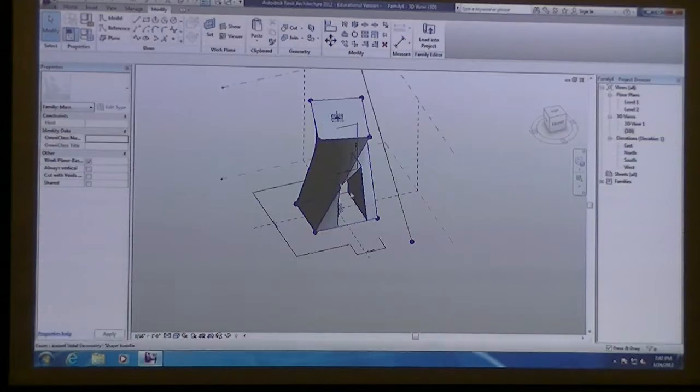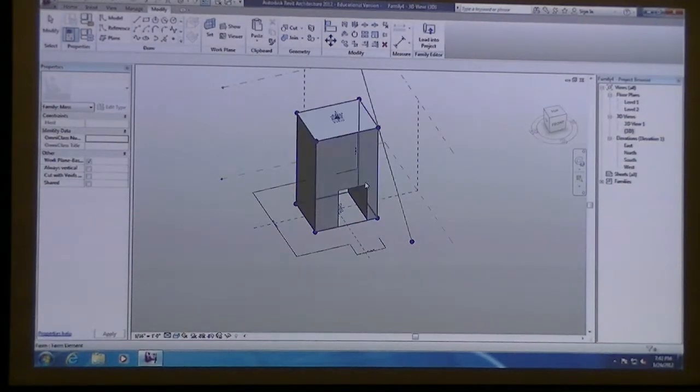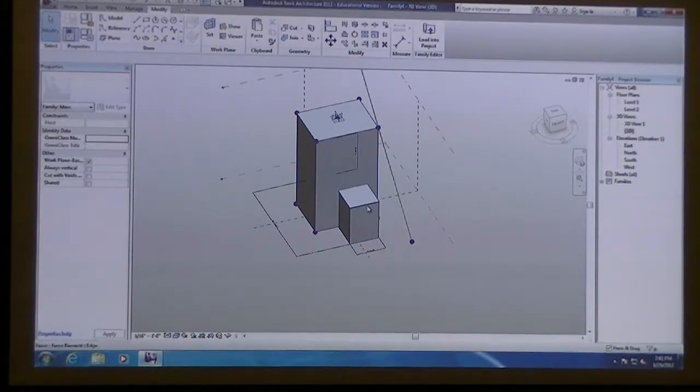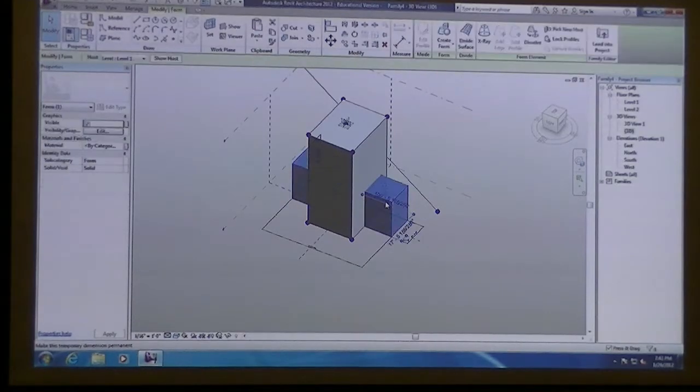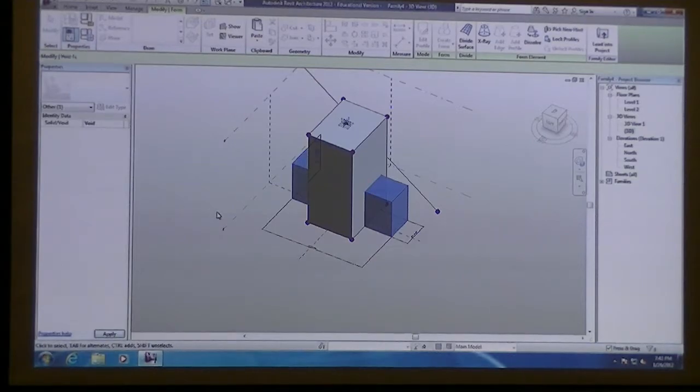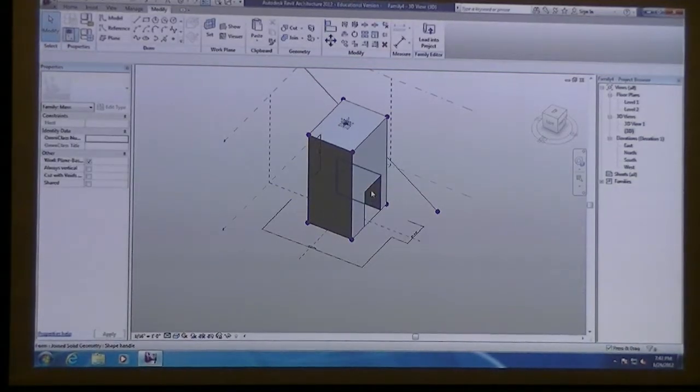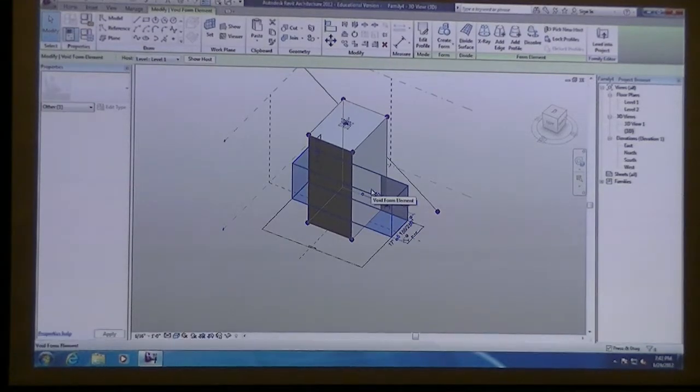The last step was to take your solid void. So if you have something that looks like this, if you tab over it until the whole thing highlights and click it, you can change it from a solid to a void. You can also keep tabbing over the empty space, and eventually you'll get the void form to show up. But you notice when you left click on it, you don't get any of the options again to change it back.